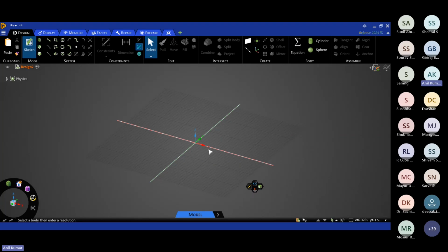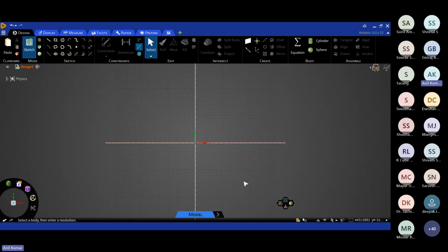If you talk about the workflow, it is very easy. For example, I'm going to perform a simulation for a beam structure where the base plate is of a certain dimension. There is a base plate, and over it we have an I beam which is welded over it, and these base plates are bolted through. So I will just take you through how this workflow works. For example, I'm going to model the base plate. So simply I will select this.